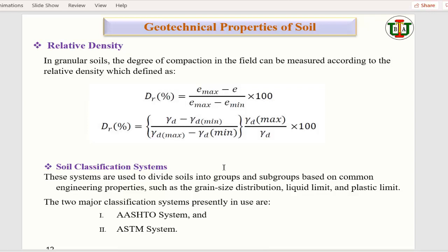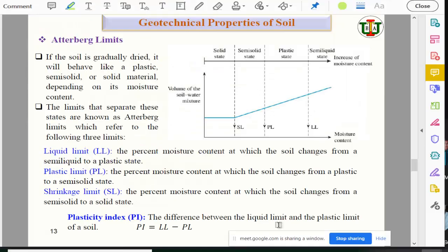And also soil classification systems; there are a few classification systems. The liquid limit is the limit after which the soil behaves like a liquid, and before that margin it is the plastic stage where you can remold, actually mold, your soil, right? Maybe you did the test in geotechnical engineering 1, where you try to change the shape by rolling the soil on a certain board.